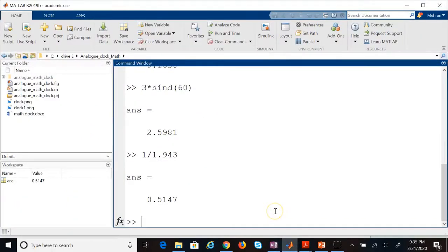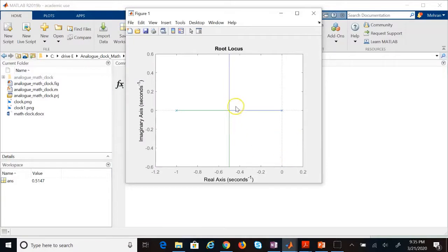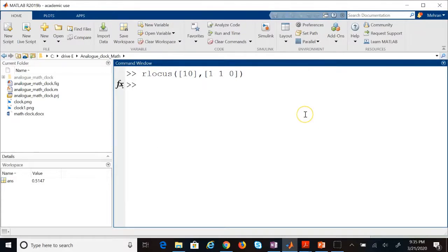And I say, absolutely, why not? So we first plot the locus of the original system, where the numerator was 10 and the denominator was s times s plus 1. This is the original system, which we have seen, the two vertical lines separated at one half. So that's exactly what we had. Now, instead, what I have this time is G times GC.